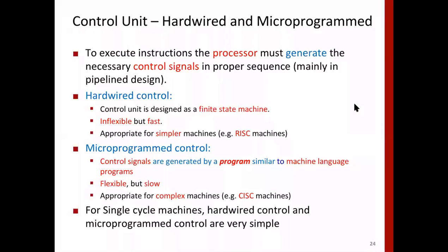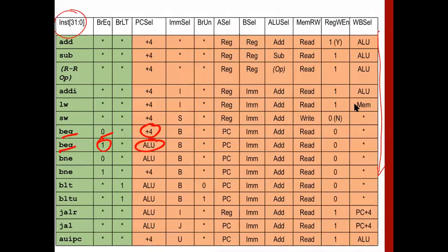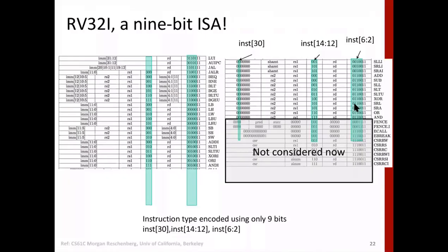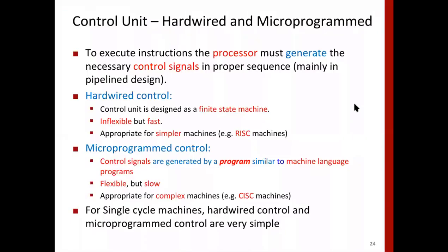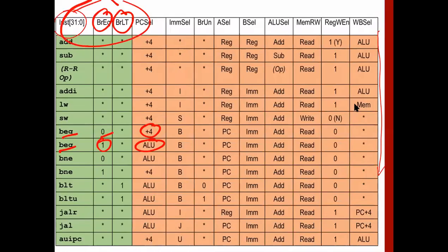First, the whole idea is that it's getting certain inputs, which are a few bits from the instruction, and BR and EQ. So basically we are taking 9 bits plus 2 bits. These are all inputs and we are generating this. So now we can do it two ways. First, we can create a combinational logic circuit, an FSM, whose inputs are these and output is all this, right?